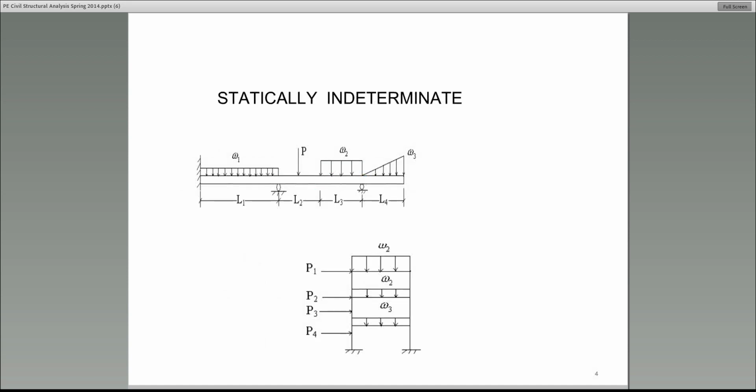Here, there are examples of indeterminate structures. So please help me out. If we look at this, Mary Hill is asking me, what is the condition at the hinge? That gives us a moment equation. So what we can do, Mary, is to write an equation of the moment around wherever the hinge is, and that would be equal to 0. All right? Very good. Excellent.